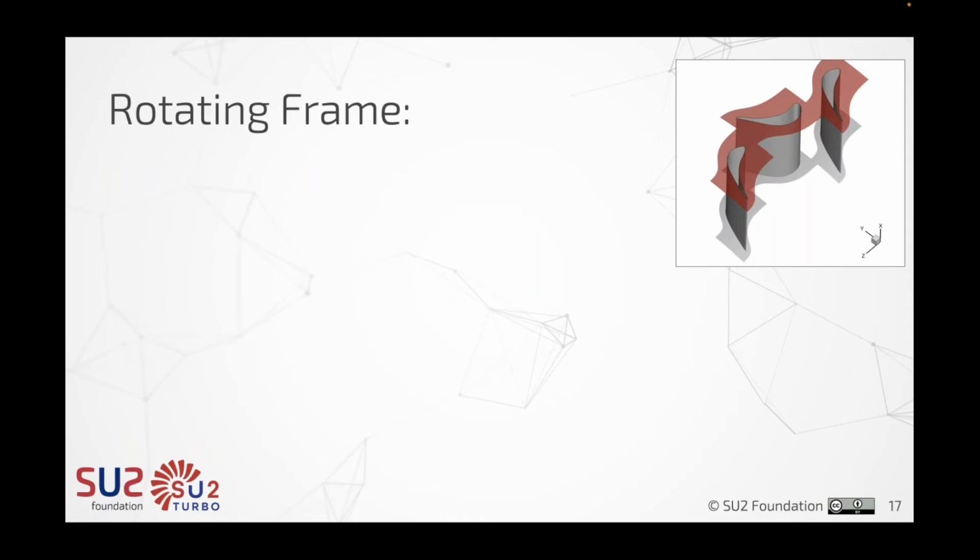Okay, then we have been talking about this rotor that rotates, and we have to specify this. Probably the best way to do this is in the sub configuration file of the zone that rotates, as we will have a master config file that you will find in the folder to which that link was pointing to, and then inside the master config file you will find sub configs for, in this case, the stator, the rotor, and the second stator.